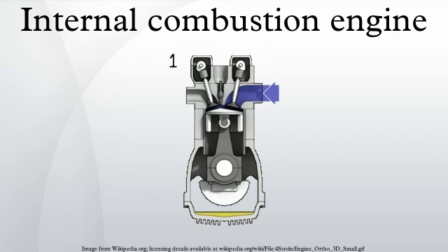Common cylinder configurations include the straight or inline configuration, the more compact V configuration, and the wider but smoother flat or boxer configuration. Aircraft engines can also adopt a radial configuration, which allows more effective cooling. More unusual configurations such as the H, U, X, and W have also been used. Multiple crankshaft configurations do not necessarily need a cylinder head at all because they can instead have a piston at each end of the cylinder, called an opposed piston design.